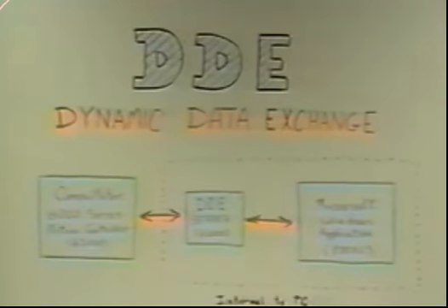Parker Compumotor has developed its own DDE servers to be used in conjunction with the 6000 series motion controllers. The DDE server will allow information or data to be exchanged between a 6000 series motion controller and many Windows applications. In particular, today we'll show you an application in which the Compumotor 6200 series motion controller, or two-axis stepper indexer, will exchange information between itself and a Microsoft Windows application, Excel. This will call upon the DDE 6200 server.